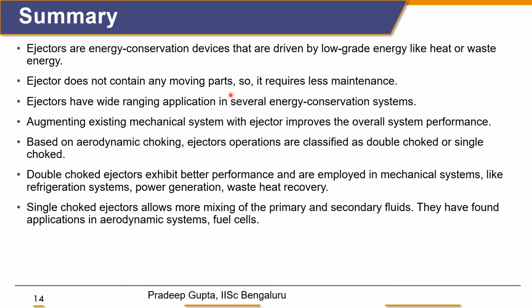So as a summary, ejectors are energy conservation devices that are driven by low grade energy like heat or waste energy. As I mentioned, the ejector does not contain any moving part, so it requires less maintenance. It has wide ranging applications in several energy conservation devices along with aerospace and mechanical domains. Augmenting an ejector with a mechanical system improves the overall system performance.